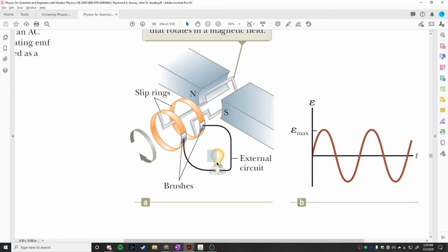The way that a motor works is you would replace this device here with a power source. Plug it into the wall, basically. And when you plug it into the wall, it has the effect of causing current to flow through here, which places a torque on the loop, which causes the loop to then rotate. You guys understand that? Basically, replace the light bulb with a power source, like plug it into the wall. It will send current flowing through the system, which will then cause the loop to rotate. And that's a motor, basically, right? And what I'm trying to say about back EMF is that the faster the motor rotates, the larger amount of back EMF you're going to get. Does that connection make sense?